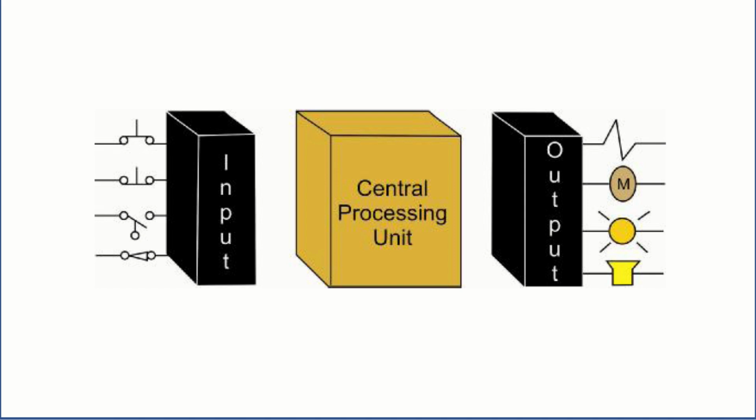Under such situations, whenever there is no object between the source and the detector module, then there will be an optical connection between them. That means whatever signal the source generates will very easily reach the detector, and the detector will generate a significant signal that can be read by the PLC.